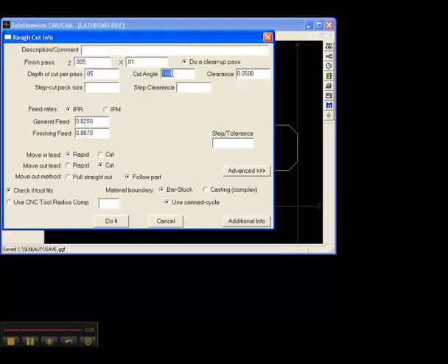When we say 180 degrees, we're talking about primarily removing the material towards 180 degrees. That would be towards 9 o'clock, for example. So 180 would be typical for an OD or an ID rough. The tool would come down in X and rough across towards 9 o'clock or 180 degrees, retract up, and then return and repeat.